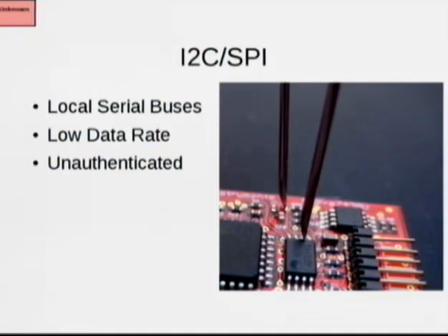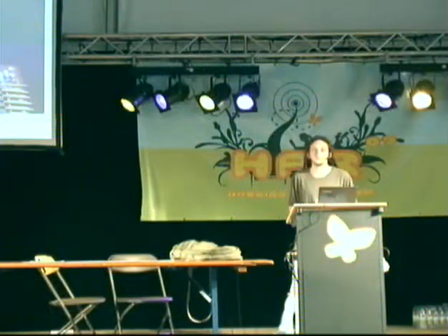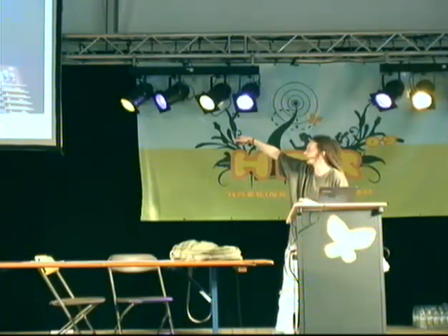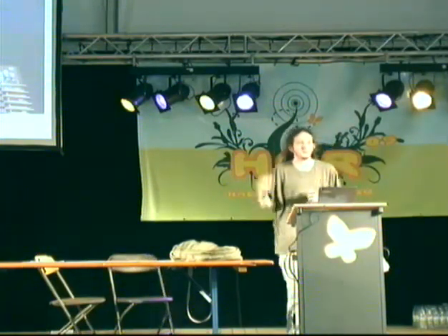This is a memory chip here underneath the laser. And then over to the left, this larger chip is a microcontroller. And these 2 are connected by an I2C bus, which is multi-master. And because it's multi-master, unless one of these chips is trying to hold the line open, you can connect to it as a second master, and you can just ask the memory chip for its contents while the board is still running. So in this case, I dumped the firmware that was contained within this memory chip just by tapping the 2 right pins on the top and having a regular I2C ROM programmer.